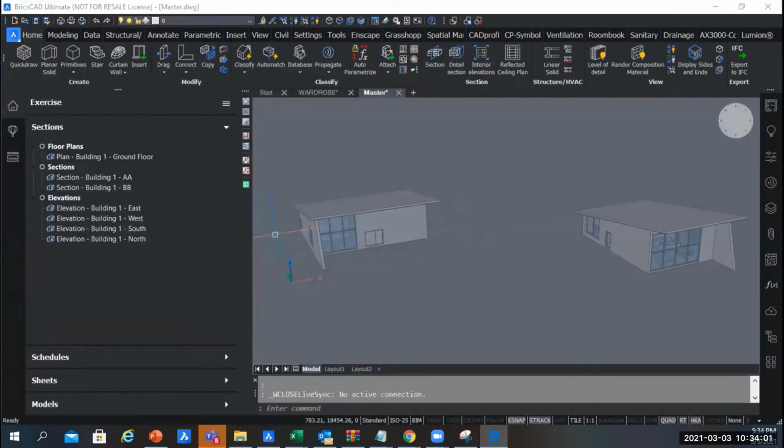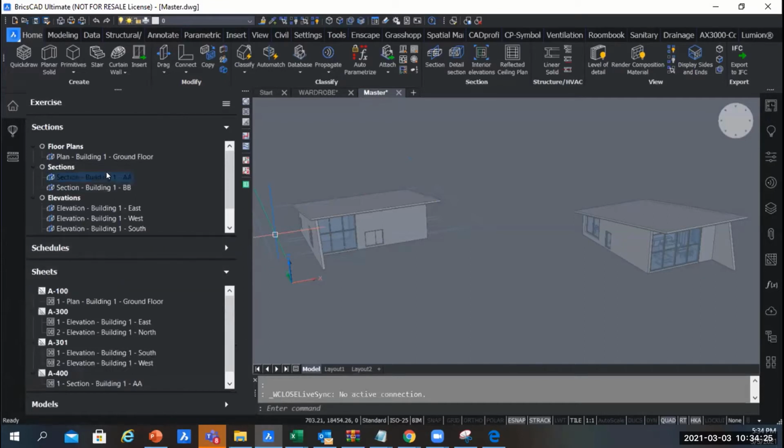So that's done. All right. Then you can also drag and drop a section onto a different sheet than the sheet which it is currently located on by dragging the section name from the section tab towards the sheet name. Okay. You can, let's say, use one of these. And if you go to your sheets, you should be able to drag these out here. Just drag it here and you see that it goes in there. Okay. So you can test that.